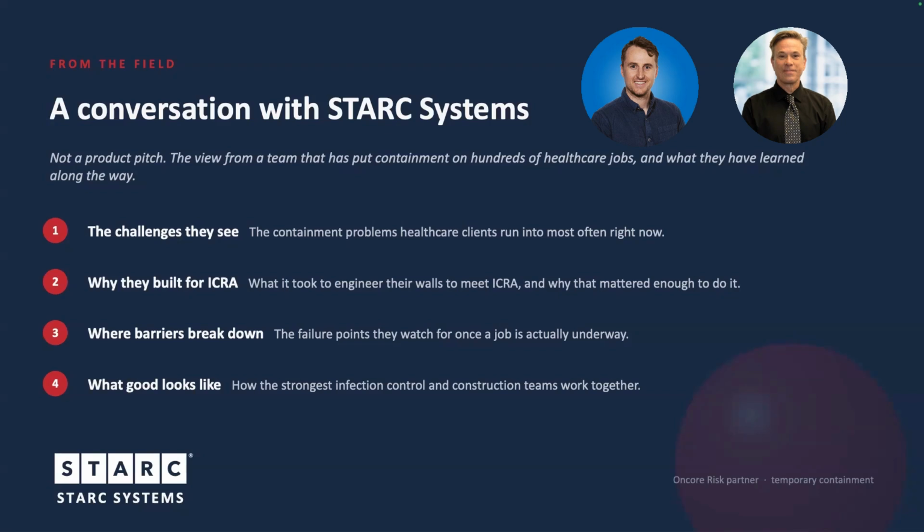And so depending on the gap that you have between the pillow and the existing structure, you fill it with a certain layer of pillows. And these are intumescent pillows. So in the case of a fire, it completely fills the void to stop fire from transferring over. Yeah, so those pillows would be the ones that expand during fire, right? Correct. And keep smoke tight as well.